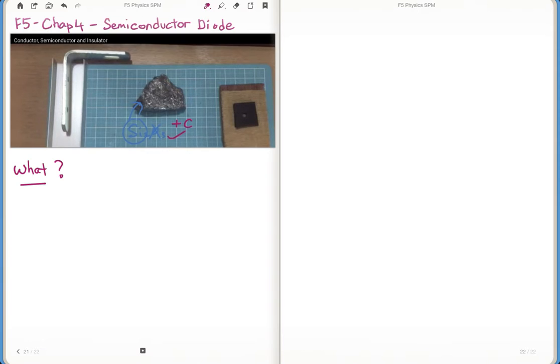The C and O combine to give CO2, and you are left with your silicon. Then they melt it, cast it, and eventually crush it into pieces. Then you may use it for other processes to make a silicon wafer. So this is a piece of metallic silicon that I obtained from one factory to show you what silicon looks like.